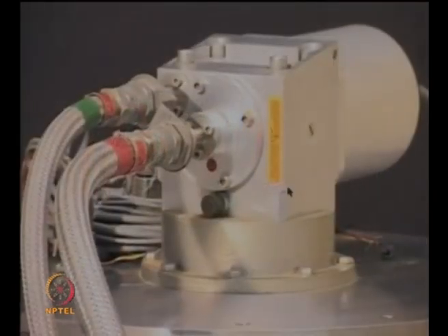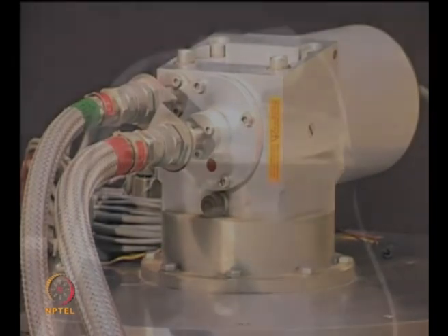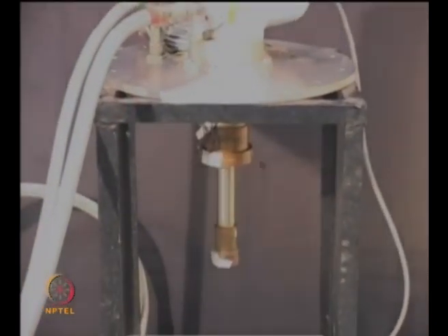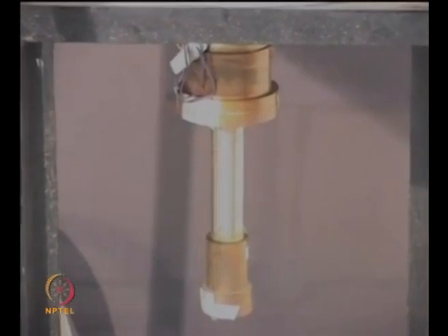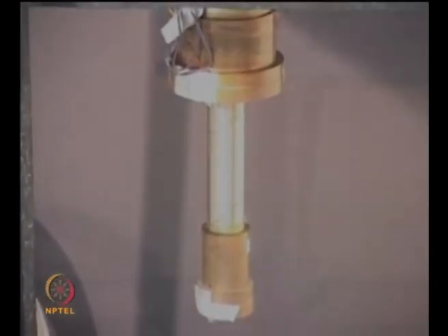All right. So, now what you see below this flange is the cold head, which is connected to this flange, and this flange will sit on the vacuum vessel, which I will show you later. So, this is the cold head now. This is the first stage and this is the second stage of the GM cryocooler. Now, this is a 10K cryocooler.